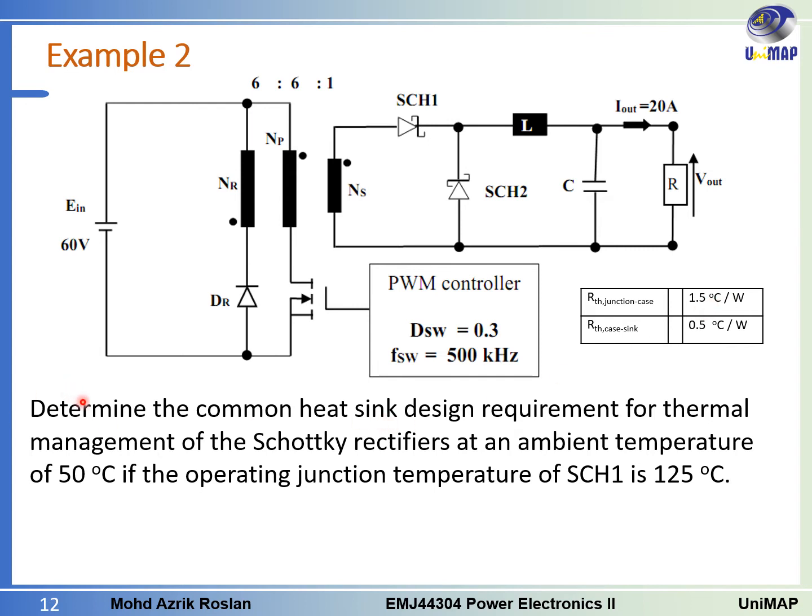In this question, it asks us to determine the common heatsink design requirement for thermal management of the Schottky rectifiers. This is the key here. Remember that this single heatsink requirement is only for Schottky rectifiers, so only for these two. If you add another one for the Mosfet, it will be wrong, because the question asks only for the Schottky diode. So you have to be really careful.